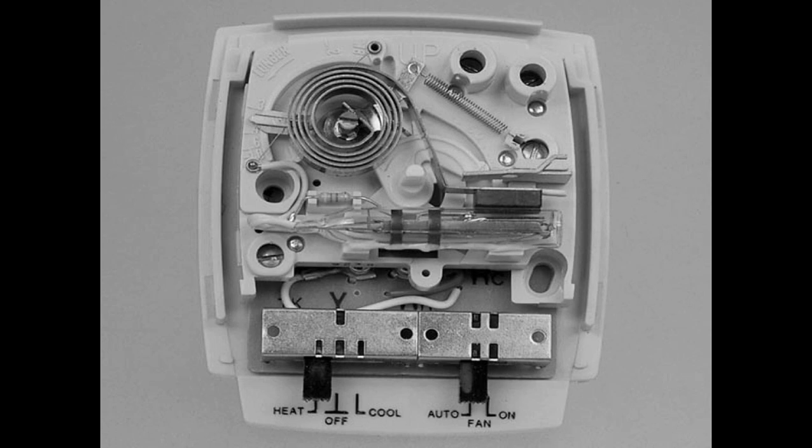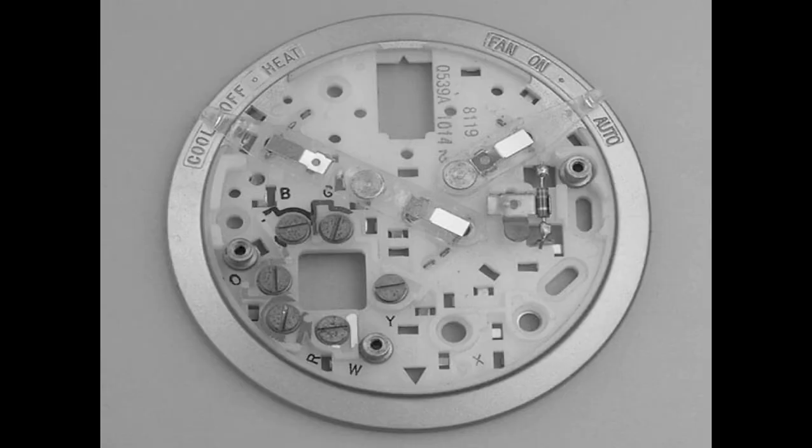Another example of a sub-base is where the thermostat mounts on the sub-base. Okay, you'll notice here you really don't have any wiring connections you can access directly from the top, which is where the thermostat mounts. All of your wiring connections are underneath. Another example of a sub-base, this is for the old round thermostats, the Honeywell T80s that you've seen forever. Okay, again, we have all our wiring connections down here.